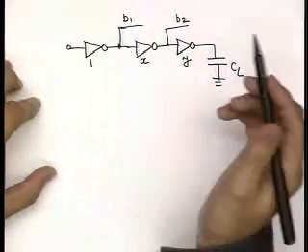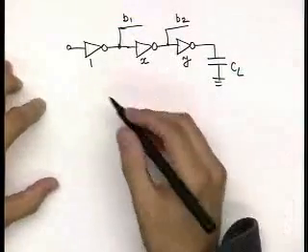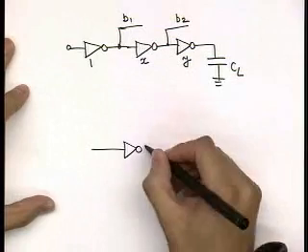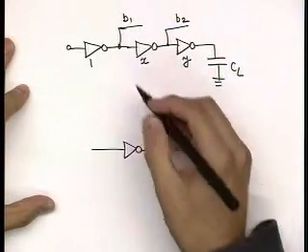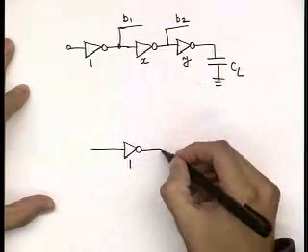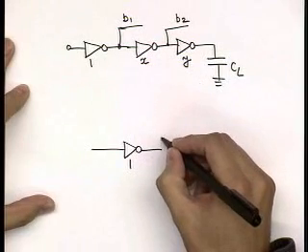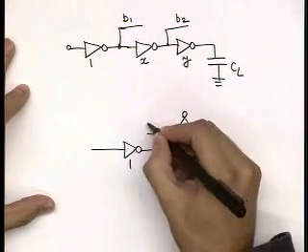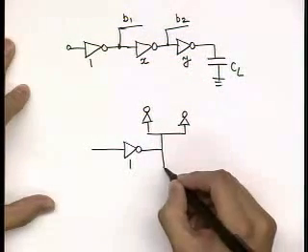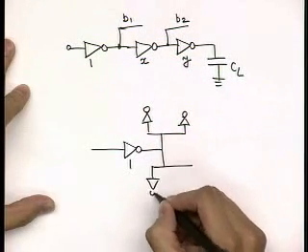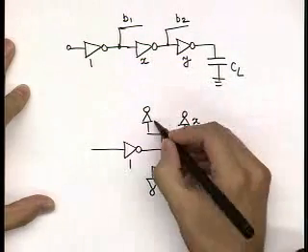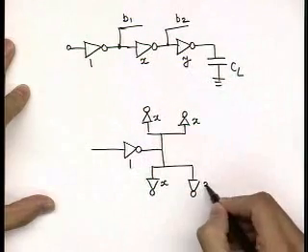This comes from the fact that when you build a clock tree, you build it in a hierarchical way. So you have this unit-sized inverter, and that guy branches off to a certain number of domains. The size of all of these is x, x, x.